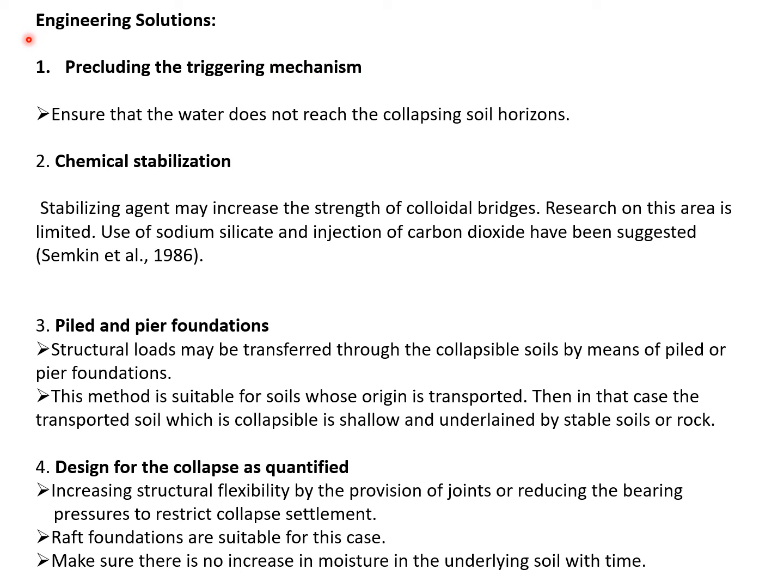Engineering solutions. Precluding the triggering mechanism: ensure that water does not reach the collapsible soil horizon. Chemical stabilization: the stabilizing agent may increase the strength of the colloidal bridges. Research in this area is limited. Use of sodium silicate and injection of carbon dioxide have been suggested.